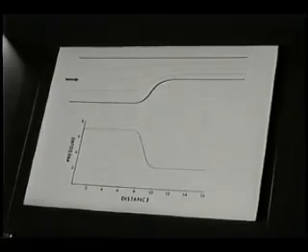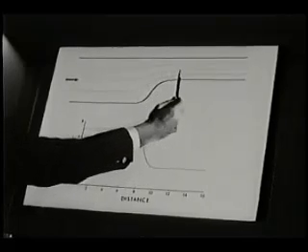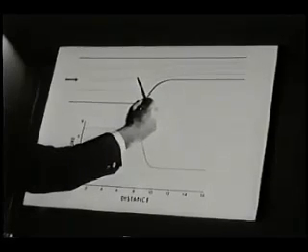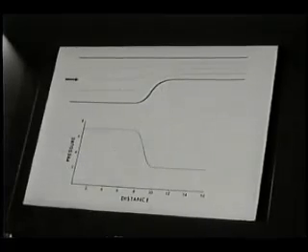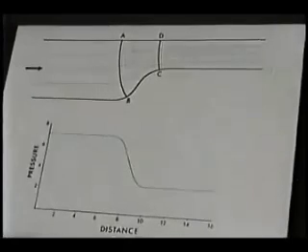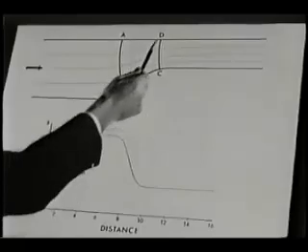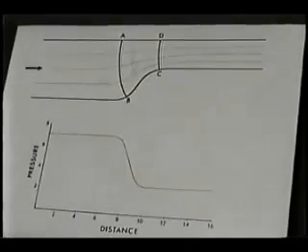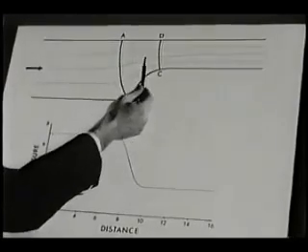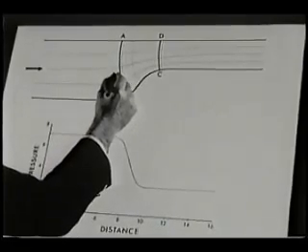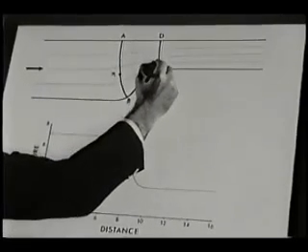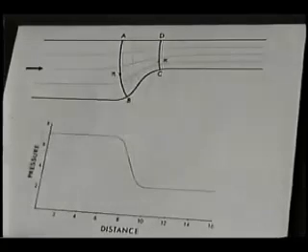These are two curves normal to the streamlines in the regions of different concavity. And these are the directions of increasing n. That is, outward from the center of streamline curvature. From a one-dimensional point of view and a comparison of cross-sectional areas, we may expect the average pressure on AB to be only slightly less than the upstream pressure.